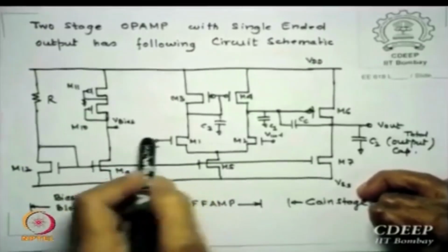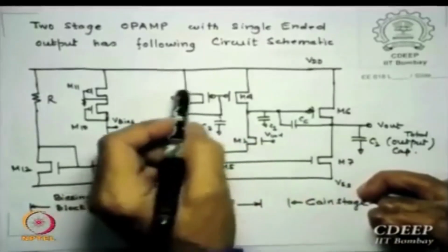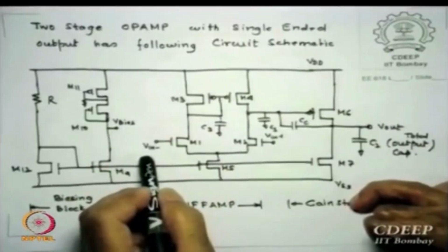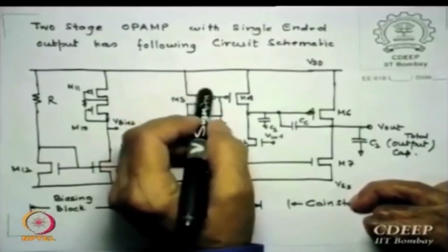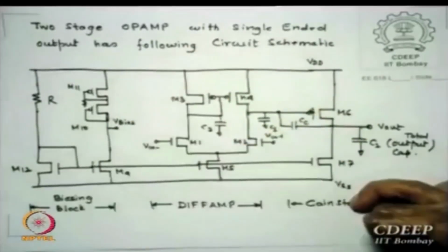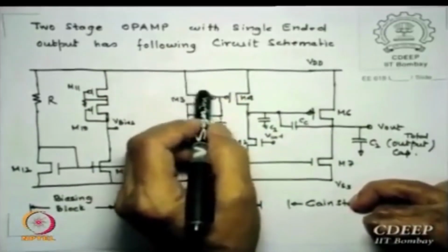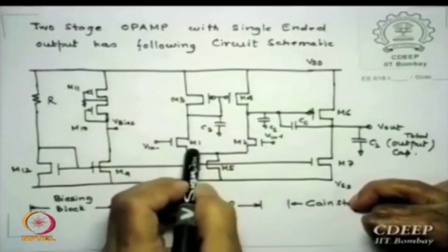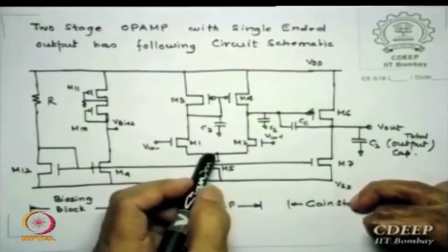Now this value has to be, for the worst case, whatever I subtract, still reach 2, which is the value given to me. So what do I say? Okay, so VGS1 I know is VT plus the square root of 2 times the current flowing through this. So I choose the maximum of VTP because that is the worst case available to me. When I calculate this, the drop is nothing but VGS minus VT, okay.